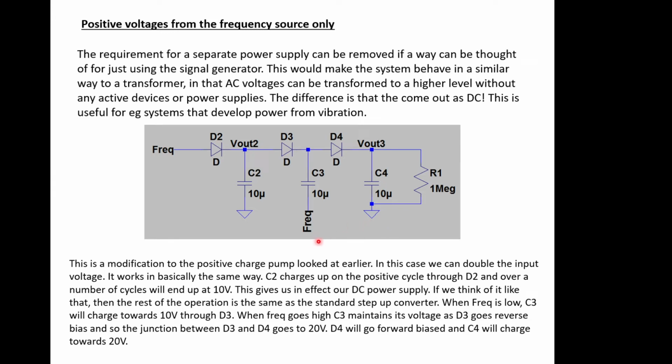But you might say, well, why don't you just power things from the power supply in the trains? Which is in fact what we said at the beginning. There are two reasons for this. First, goods wagons don't actually have any power in them at all, which was a surprise to me, and there are a lot of goods wagons around. And secondly, on passenger trains where there is power, any system that connects into that power supply has to be guaranteed to be absolutely safe, because railways are paranoid about safety. That takes years to pass all the tests, and millions of pounds, to allow anyone to plug anything in to the electrical systems of trains.